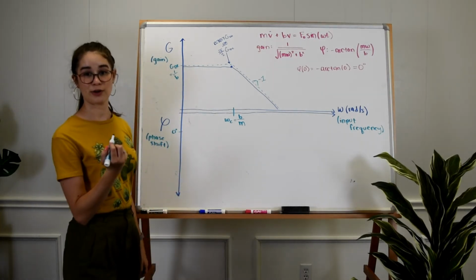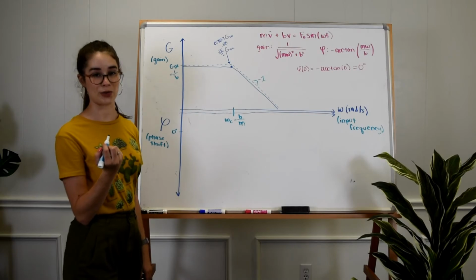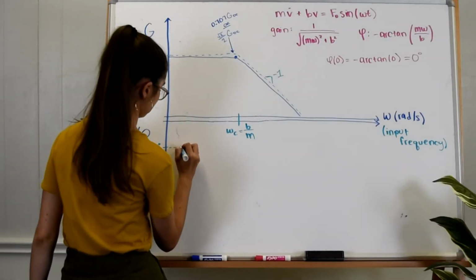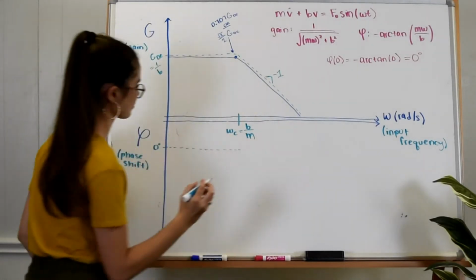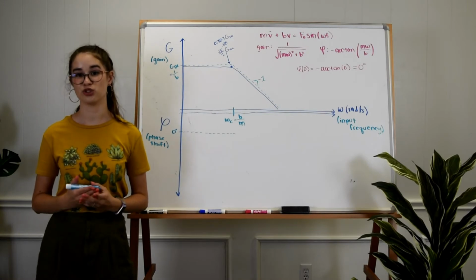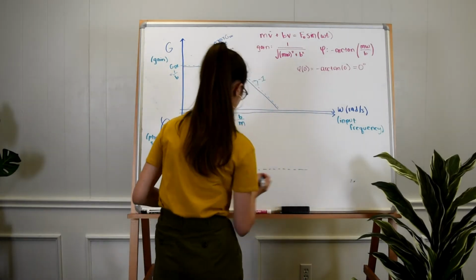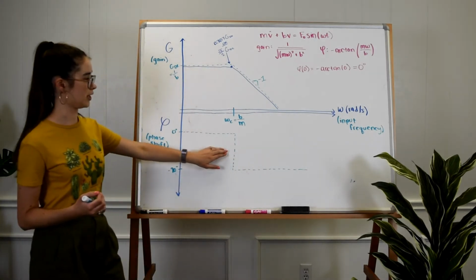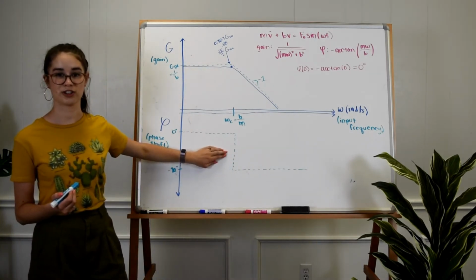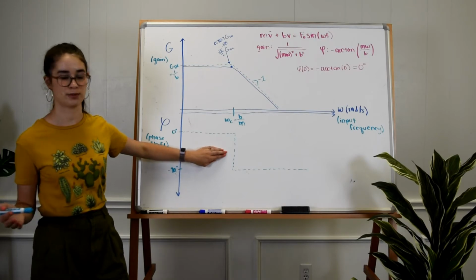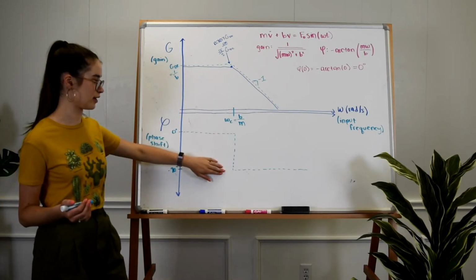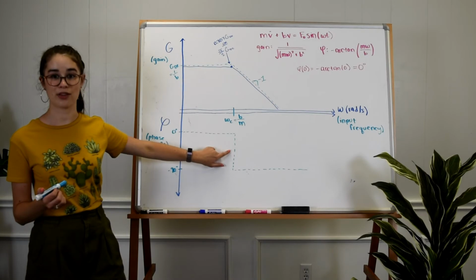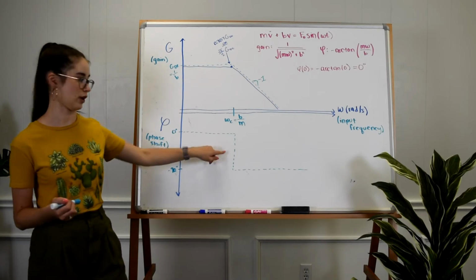And then we draw out a horizontal asymptote until we hit our corner frequency. At this value, our phase shift will drop to -90 degrees. We can now draw in our line to follow our asymptotes, making sure that at the corner frequency, our phase shift has transitioned half of what it's supposed to. So since it drops to -90, we just need to make sure that at this point it passes through -45.